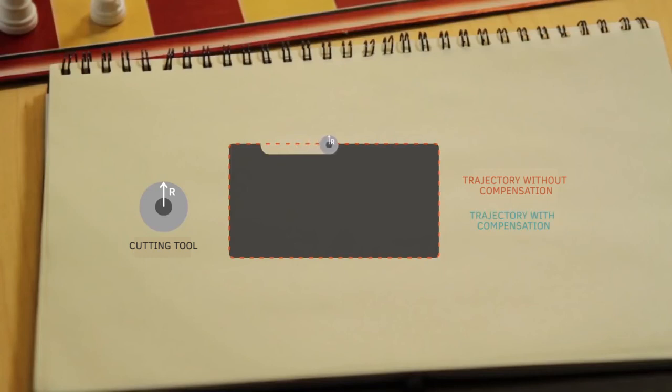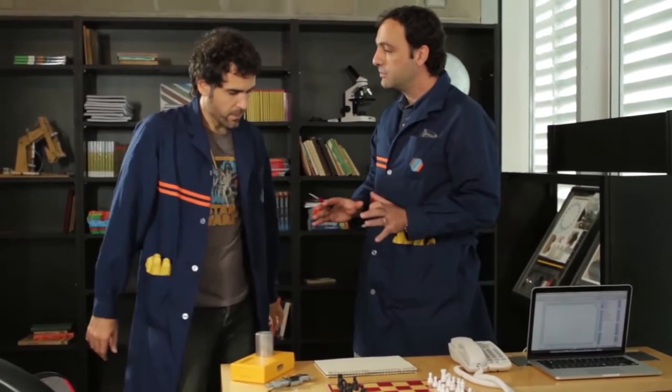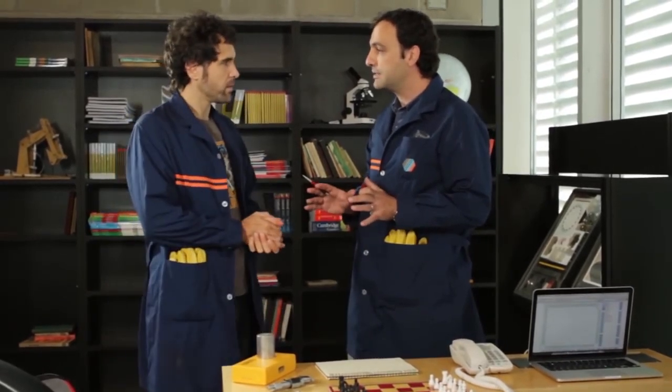We define the trajectory on the profile of our piece. Now then, the tool that is going to machine has a small tip radius. Now, this small radius that we have here, we have to compensate it, because what we're defining with the trajectory is the center of this radius. To compensate it, what we have to do is move this entire trajectory outwards, one radius. One radius. Perfect. Yes, do you understand? Yeah. Well, perfect. And with that, we're able to start.